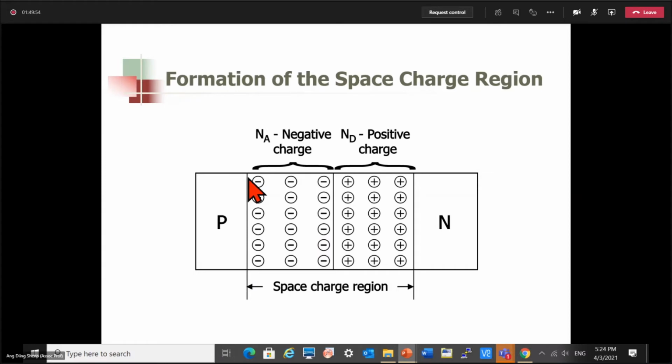It serves as a boundary where the electric field is known. It is zero, because when you move out of the space charge region into the neutral region, there is no electric field. So the electric field must go to zero at this boundary. We use this knowledge to find the integration constant when solving the Poisson equation. Okay, thank you.